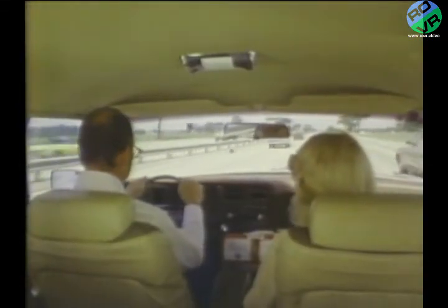Road testing to isolate driveline unbalance or misalignment involves about the same procedure used to isolate wheel and tire balance problems. Operate the vehicle at a road speed where most of the disturbance is present. Then, increase the road speed about 10 miles an hour.